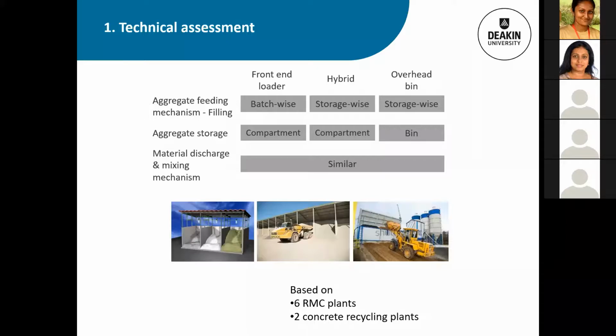With that, the mix design needed to change. You needed to account for variability, increase safety factors like the target mean strength, and use a higher plasticizer dose to reduce the impacts of high water absorption. Supplementary material was also added, because the literature discussed that fine supplementary cementitious material improves quality. So a few mix scenarios were simulated based on the published work.